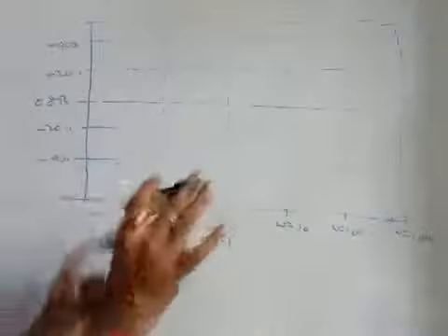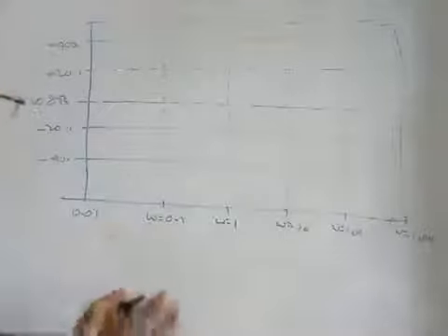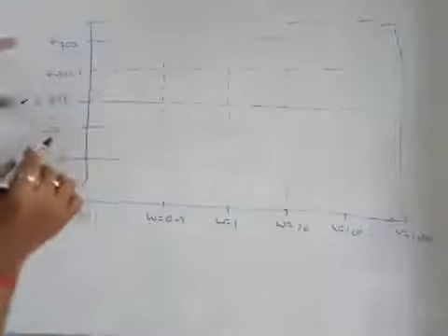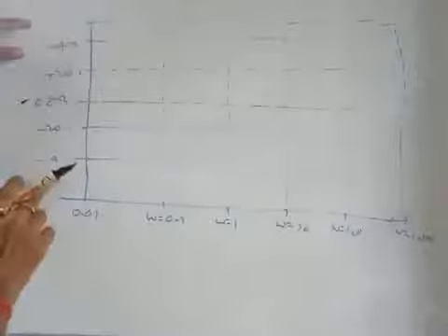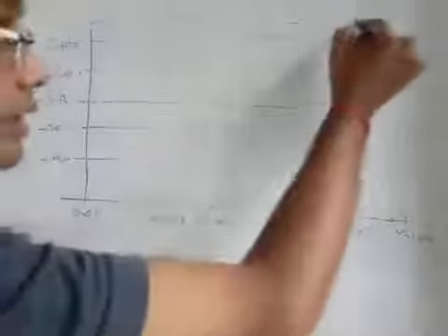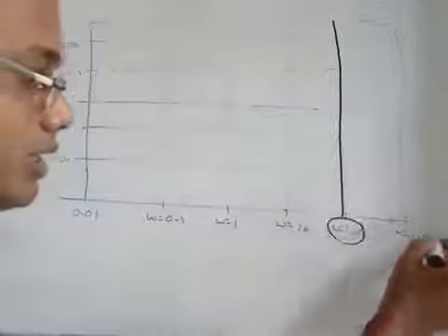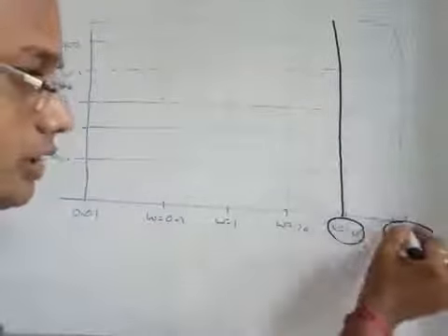See, this is the semilog graph paper. You can draw it in semilog graph paper itself. Now this is your 0 dB line. This is plus 20 dB. This is plus 40. This is minus 40 dB. And this is our reference section, right? Say we will take the last decade. This to this is 1 decade.